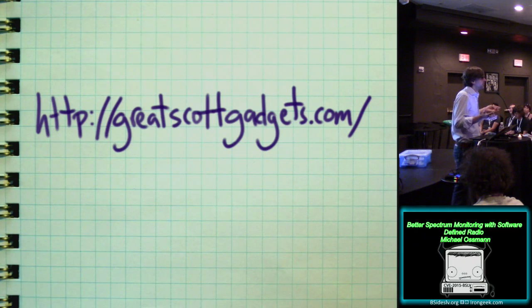Also things to consider, like the polarization of the signal. Is it horizontally, vertically, circularly polarized? What direction is the signal coming from? There are all kinds of measurements we can make beyond just the stuff that I've been talking about. If we want to monitor spectrum on a large scale and observe how it's used, it might be nice to know where the signals are in addition to what they are as detected from a given point. So all those things can be accomplished theoretically with multi-antenna techniques, either by switching between antennas one at a time or by using many antennas simultaneously.